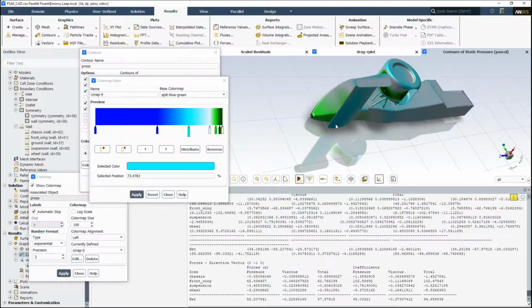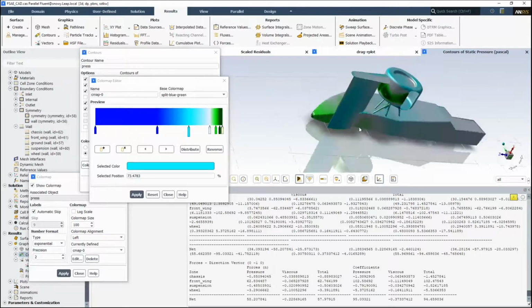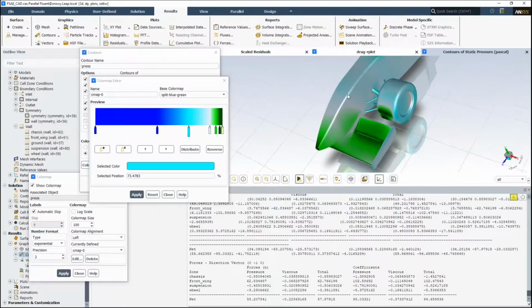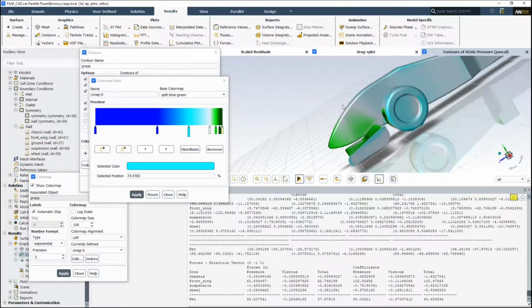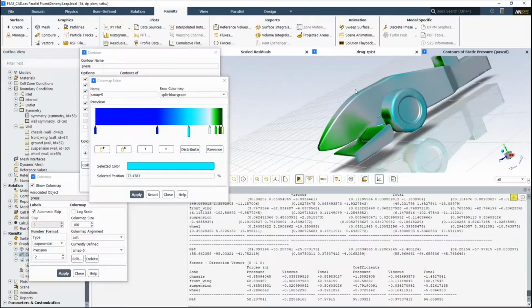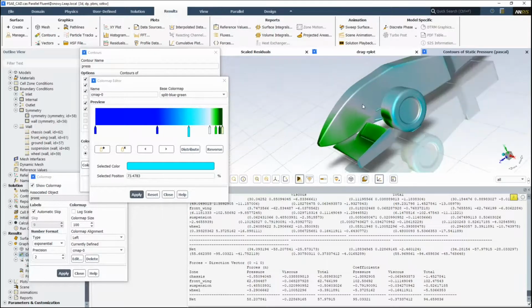Let's flatten the bottom out. Let's not allow as much air to get into here. And maybe let's keep this kind of bubble region to see if we can keep some suction under here. Maybe get some venturi under here. Also, we might try and spoil the flow along here, or change the shape so it's not so bulbous, not so airfoil shaped, because that airfoil shape, as the flow stays attached and increases in velocity, is what's reducing the pressure and causing that suction up.